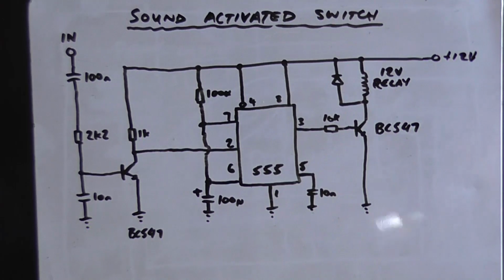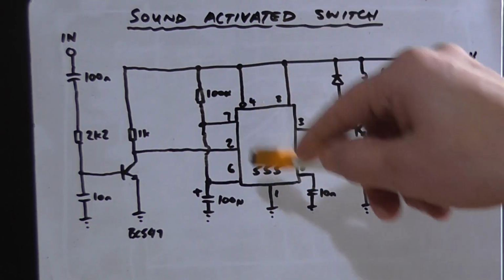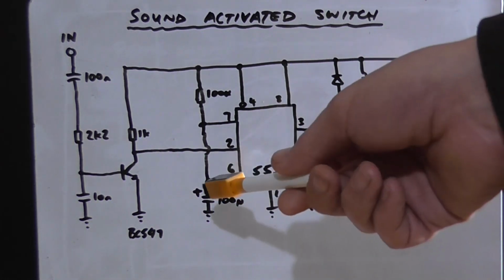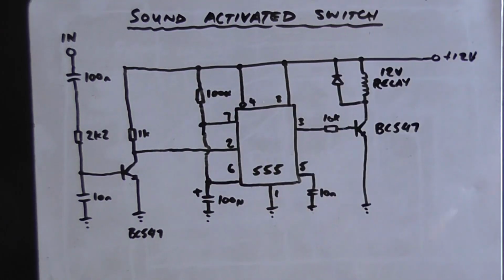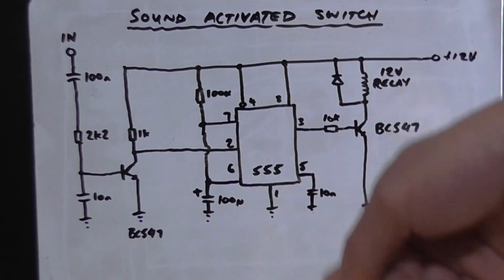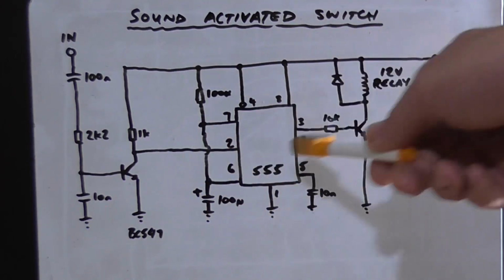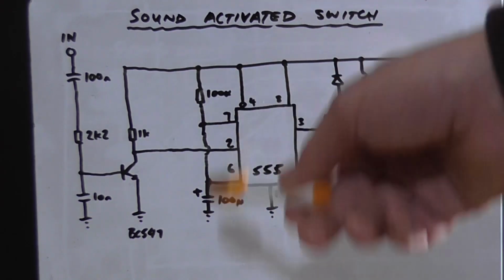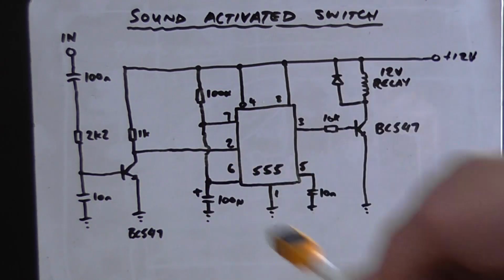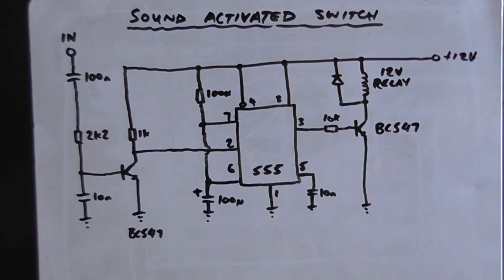Let's try that again. I'm going to build this 555 circuit part up first and test it, just to see how it operates, and if the timing constant is 11 seconds, thereabouts. There is a calculator online you can use to calculate that. Supply voltage is kind of irrelevant. And just for the trigger pulse at pin 2, I'll simply bring it to ground to trigger this circuit high. So let's get building.